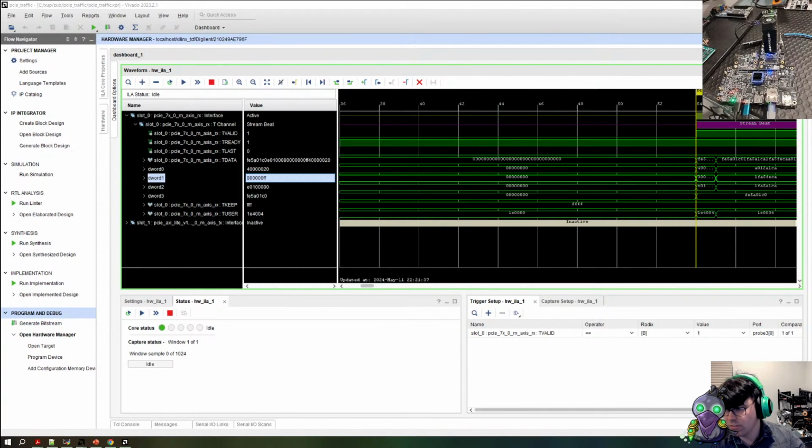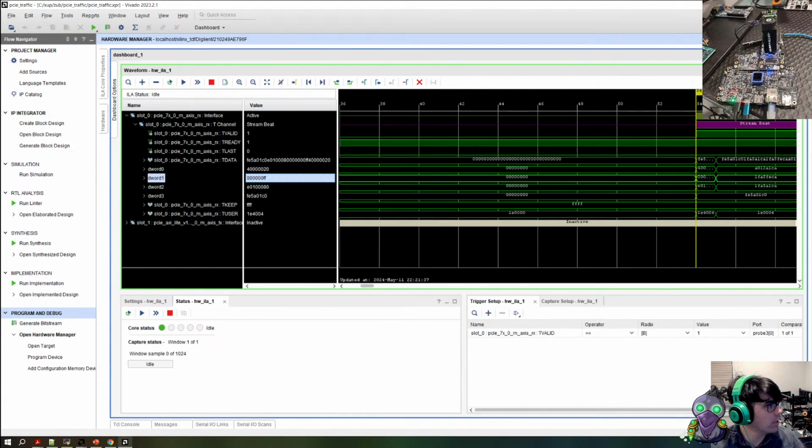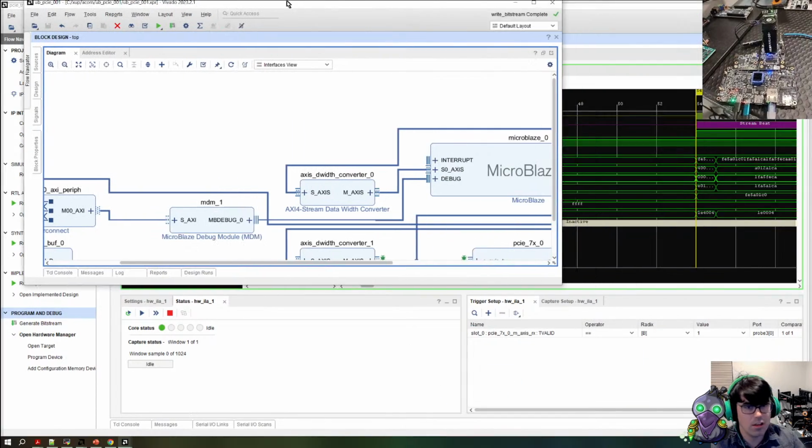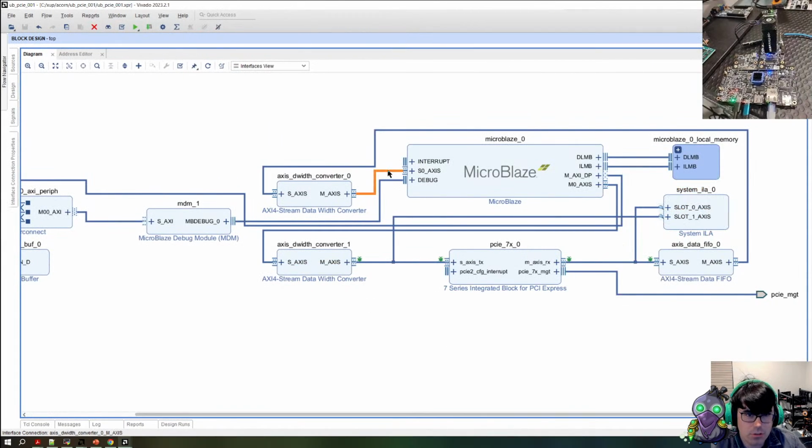So the microblaze interface is a direct AXI stream, right? So these commands allow us to read and write, not that one, this one. So those microblaze commands allow us to read and write to this. So we're controlling the endpoint in this situation mostly. The microblaze is reading the raw TLP packets for the endpoint, and we are going to attempt to write the raw TLP packets back.